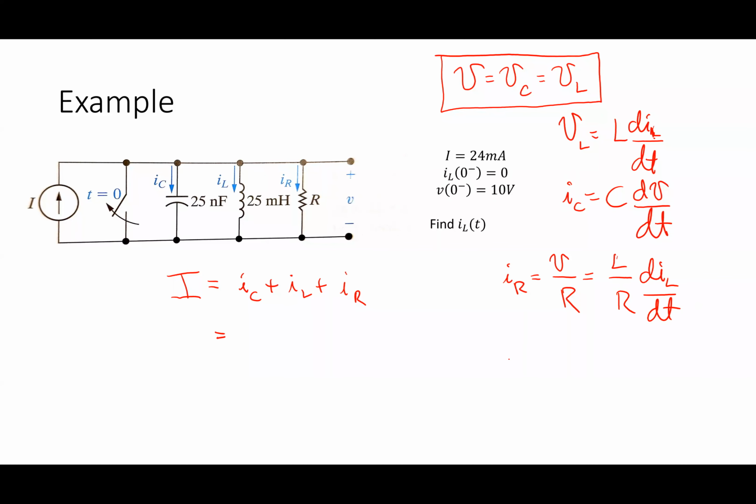And with the capacitor current, how can I get that? It's just going to be the derivative of VL. Yep, the derivative of VL. So that means it becomes the second order term, LC d squared IL by dt squared.